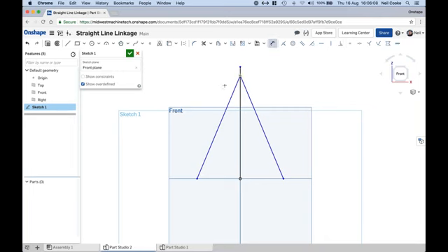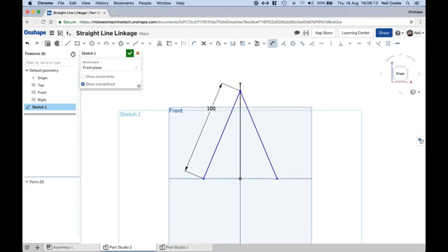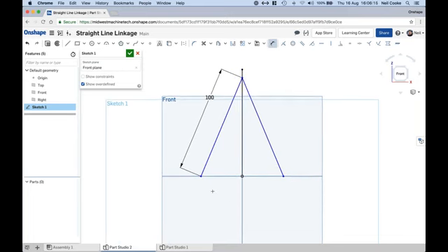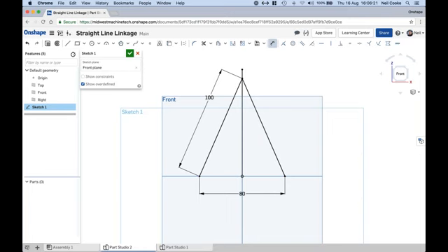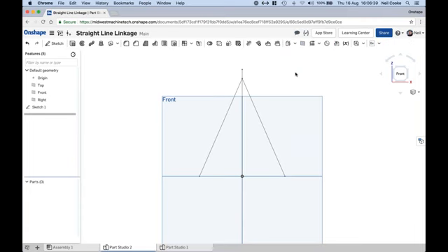Okay, and if you want to, it doesn't really matter, but I'll do it for this instance. I'm going to give that a specific length and also either a position, a distance, or an angle between those. And I just want to make sure that it's a fully constrained sketch. I mean, it doesn't really matter if you leave it unconstrained. It gives you perhaps a little bit more flexibility later as you're trying to iterate the linkage to get it exactly how you want it. But essentially, those are the three positions that make up my first shape.